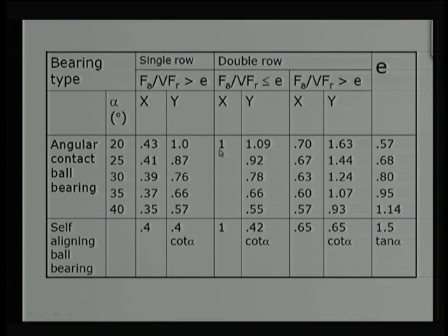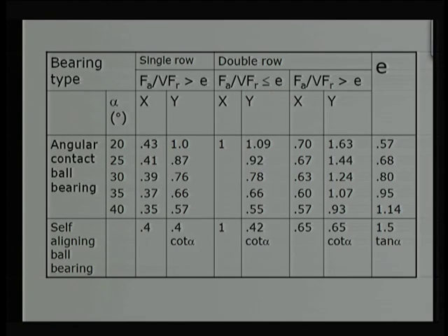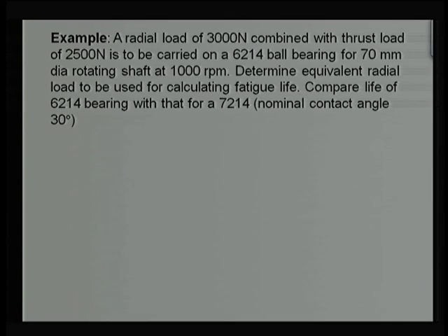So based on that we can find out the equivalent load and choose a proper bearing, and I am going to show the deep groove ball bearing and angular contact ball bearing comparison. The deep groove ball bearing, which is generally a typical choice of designers, may not be a good choice when we think about science, when we think about proper tribological knowledge. For that purpose, I am considering this example.